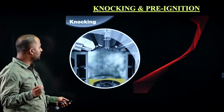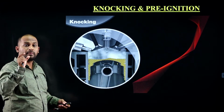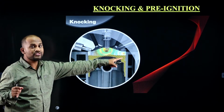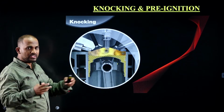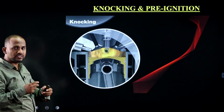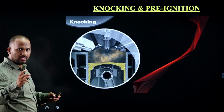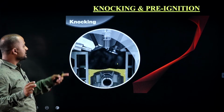But because of the abnormal combustion, in the case of knocking, what happens? First, a primary flame is created with the help of a spark plug, which leads to the creation of a secondary flame because of the auto ignition of the particles. Because of the collision of the two flames, highly intense vibrations are created inside the cylinder, which damages the system and also decreases the performance of the system.